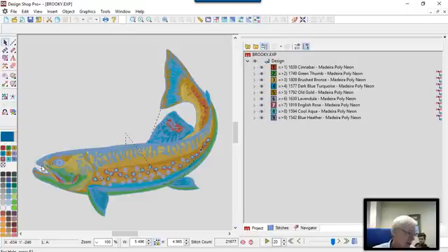It's expanded format, and you can see the colors are pretty bad. So a lot of times also we get asked, well, why do the colors always come in like this? The reason is in EXP and DST files and some of the other expanded formats, the file structure is incapable of storing color information. So when anybody opens an expanded type design in DST or EXP, they have to display something. So we pick red as the first color, green as the second, gold as the third, blue as the fourth, as you can kind of see. And every design that you open up raw comes in those colors because, like I say, there's no way that the file can hold exact thread color information.